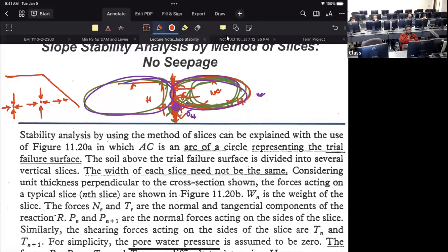Okay, if I go here at this point, a little bit far, now you have some overburden on both sides. So let's say you have the left one and you have the right one. If you look at different points, which are the points that will have more impact and which are the points that have less impact in terms of sigma v and sigma h?